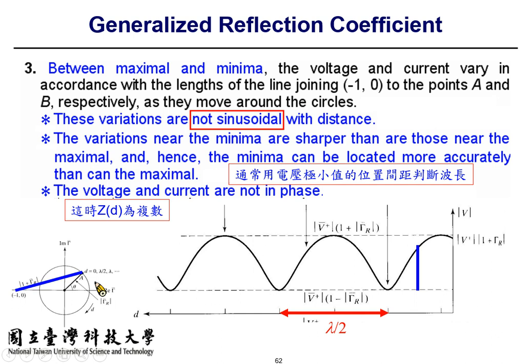Because the voltage minimum didn't reach 0. The voltage minimum is somewhere above 0. Which means the incident voltage is somewhat larger than the reflected voltage. Then this can be demonstrated with this. The incident voltage is assumed 1. That's the reason why the red arrow is that long.